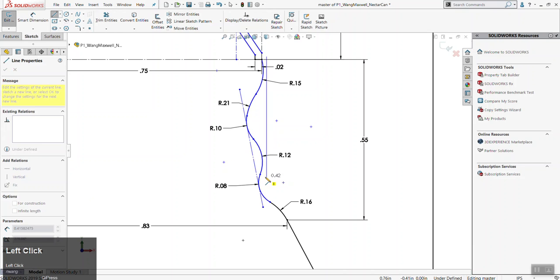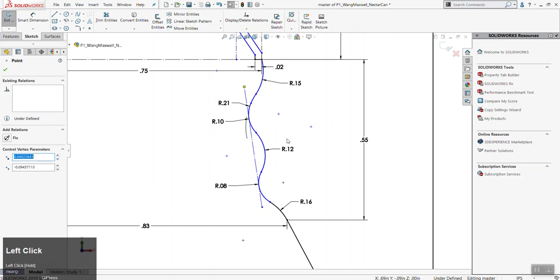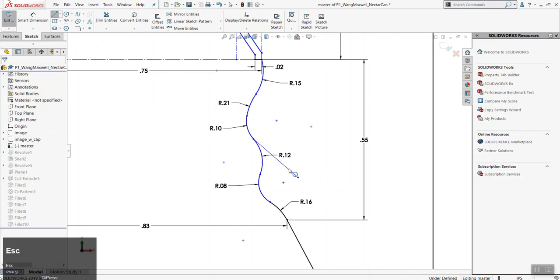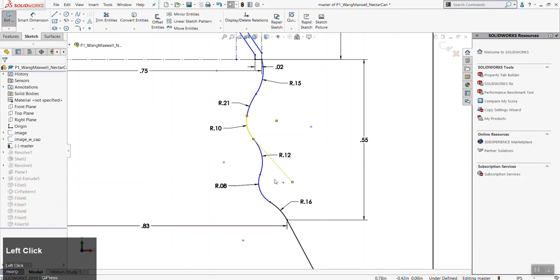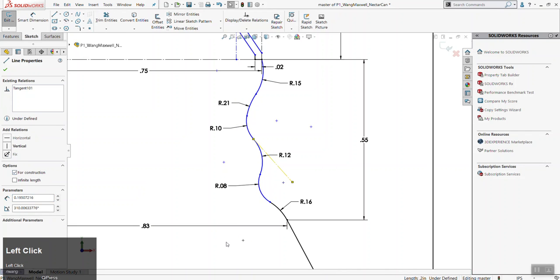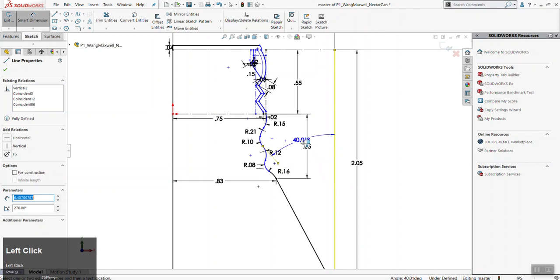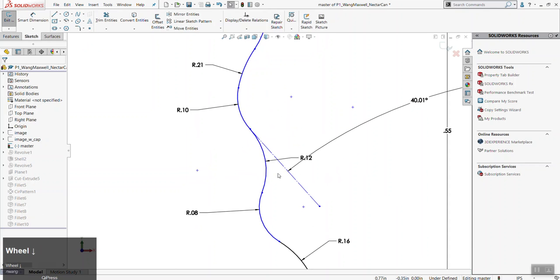But do you see how making lines that are tangent to the sketches can kind of constrain them? These are the centers that I was talking about here. So that's another way to constrain it. I think this came up in our discussion thanks to Anastasia's sketch, but this would be my preferred method: making these tangent and defining this as an angle to probably the bounding box is maybe what I would do. And hopefully that would then be fixed. Now again, if this is tangent to this, you might have to do a couple more. One may not be enough.